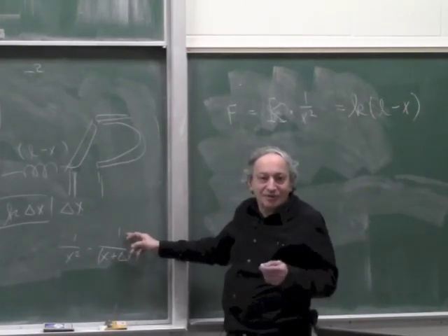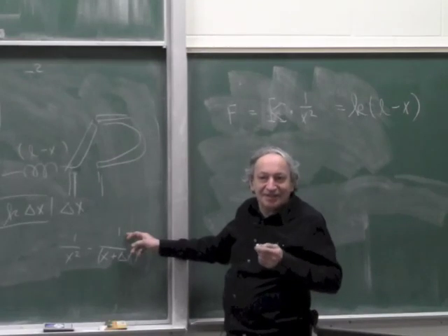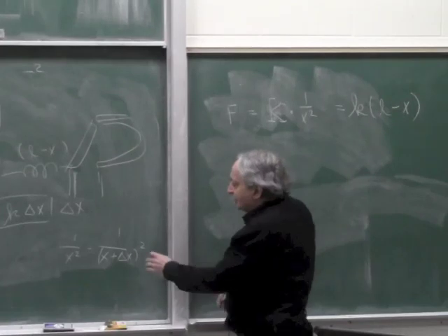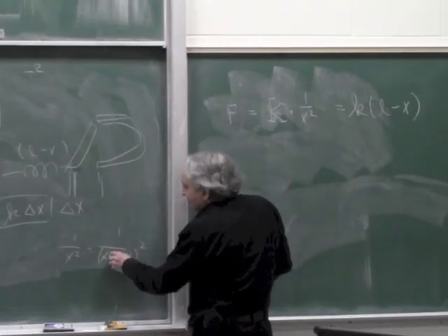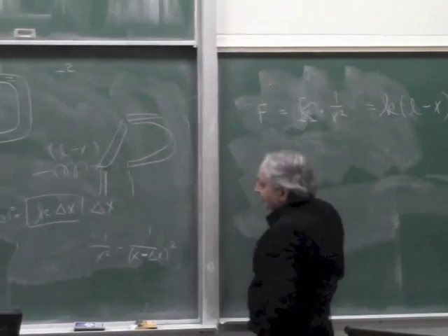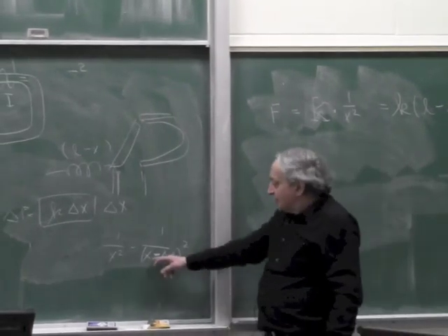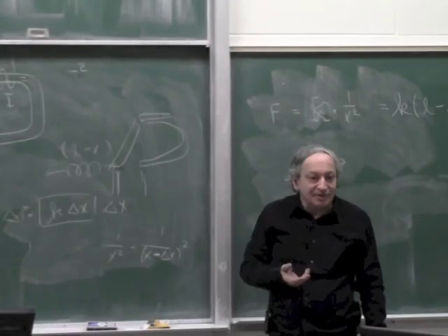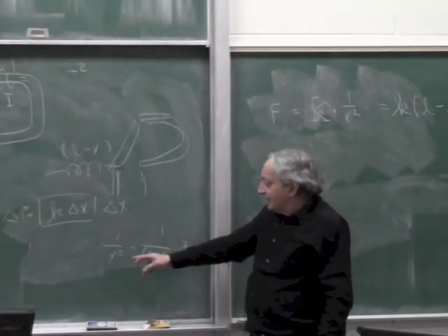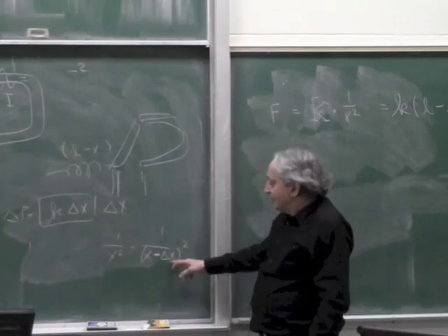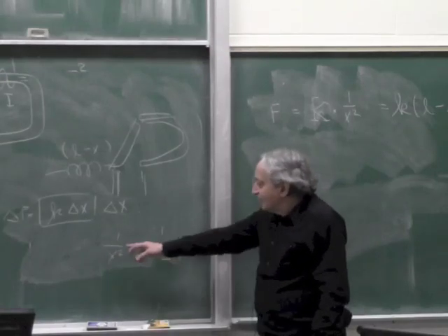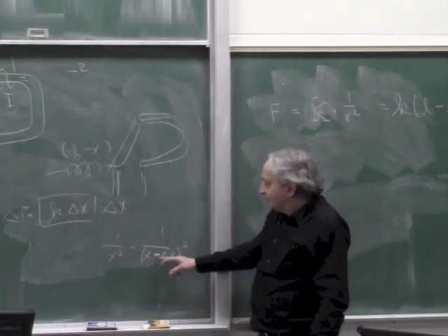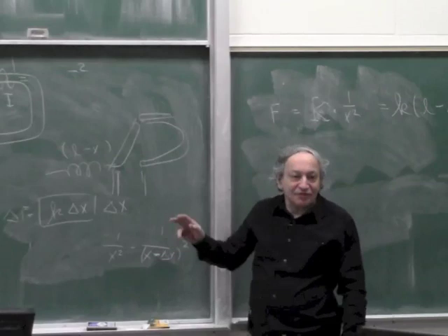So not only is the force nonlinear, but the increase in force when you add delta x or remove delta x, actually here x minus delta x, I should draw it with minus because the x goes down. So if x is much larger than delta x, this number can be as small as possible. Imagine if this is a centimeter and delta x would be a micron, this increase in force will be less than that. But when x approaches 0, this increase in force will approach infinity.